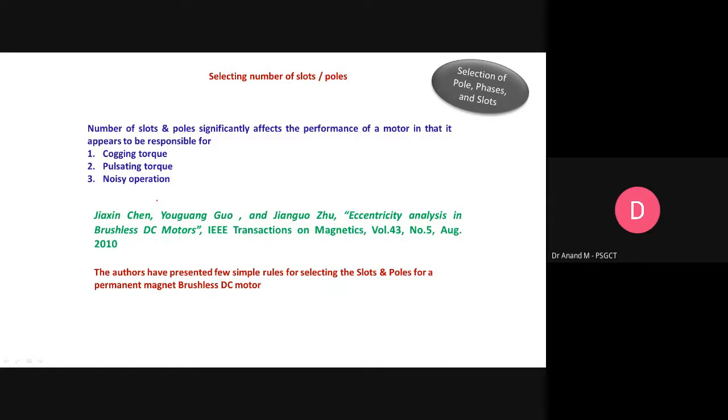Normally we say the stator core houses your entire ampere turns, your entire flux linkages that are produced by your windings, which are the balanced distributed windings in the stator core. So in a nutshell, we can say that the selection of the total number of slots in your drive stator is going to be a crucial thing in the overall design of your system.